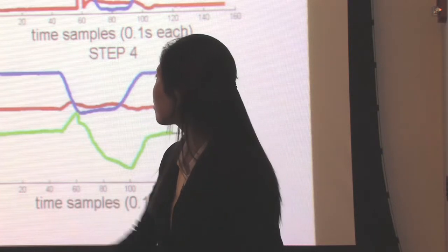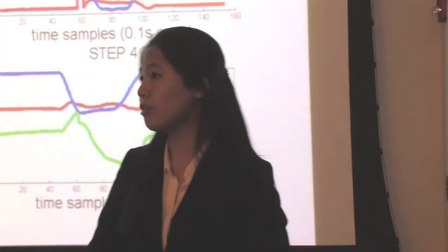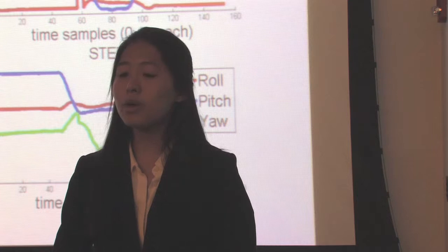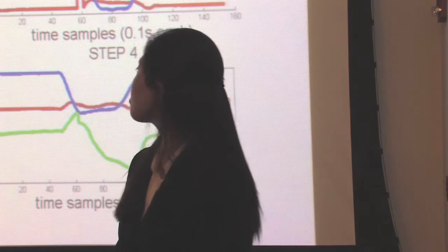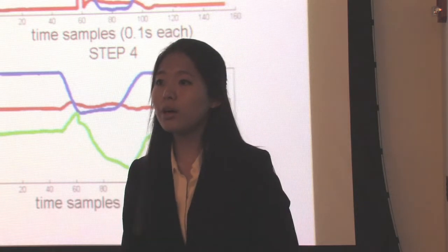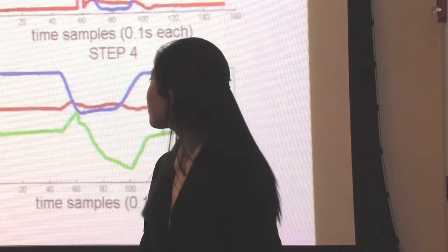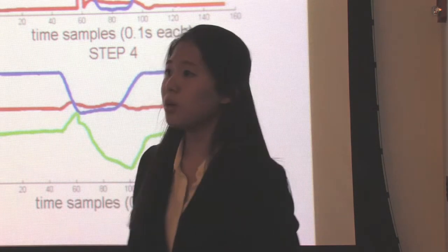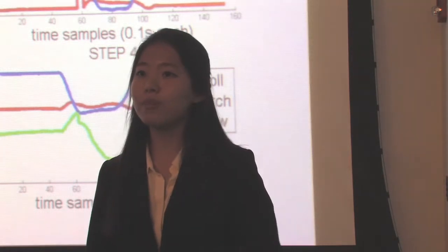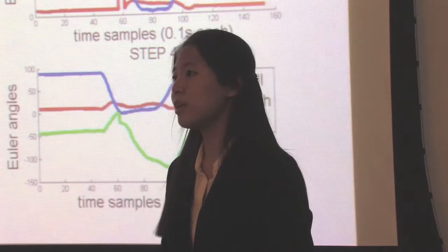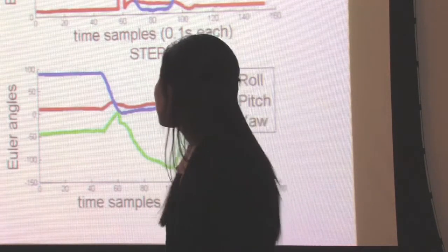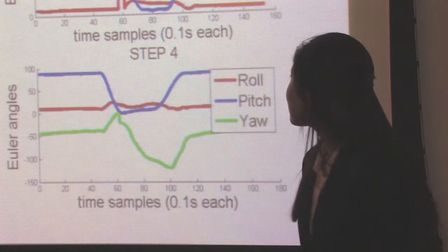One is that for roll and pitch, which are red and blue, those numbers always start from the same place. For instance, roll always starts from 0 degrees and pitch starts from 100. Meanwhile, the yaw tends to drift and starts from a different number each time. We believe that this drift came from a glitch in the gyroscope that was embedded in the InventSense beforehand.